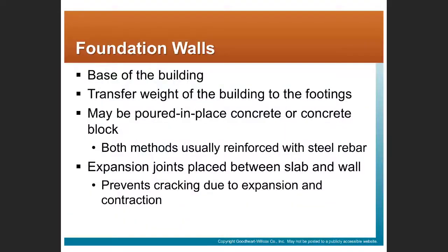We're going to come back to green building at the end of. So again, we talked about the footing. The foundation wall is the base. We're transferring weight from the structure to the footings. The foundation walls can be either poured concrete or concrete block. In both cases, we're going to be using rebar.